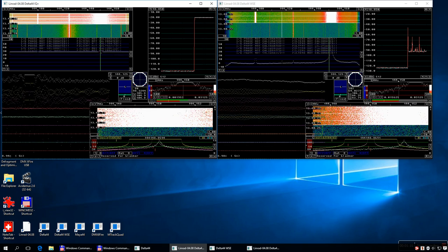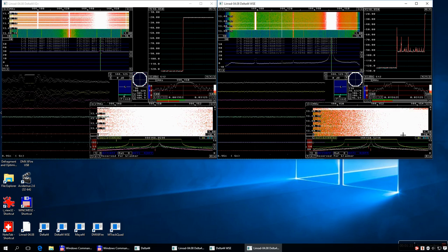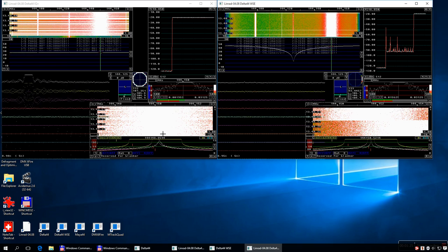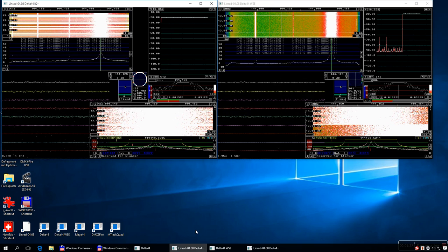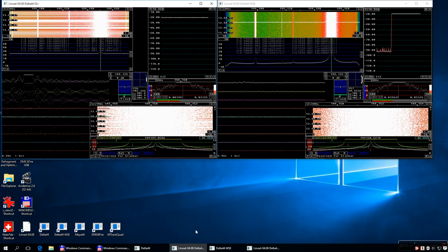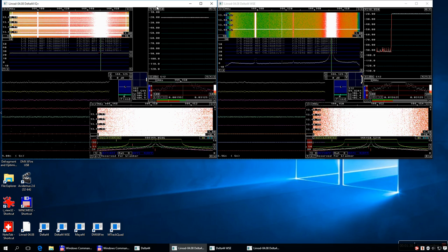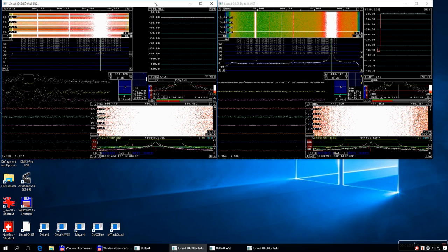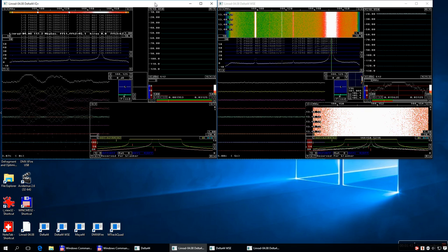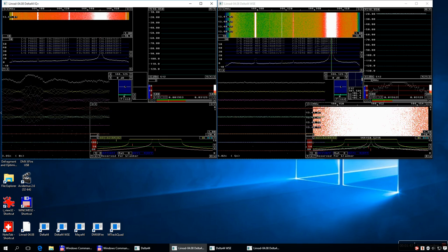I now inject a very strong signal like that, and I have to have it in the passband center now here, and this one is already close to centered. The frequency, I haven't worried about calibration. Now, under Windows 10 there are now and then problems with glitches when running two Delta 44 sound cards, so I have to exit and then go back to get the correct readings. And again click on the signal, of course.